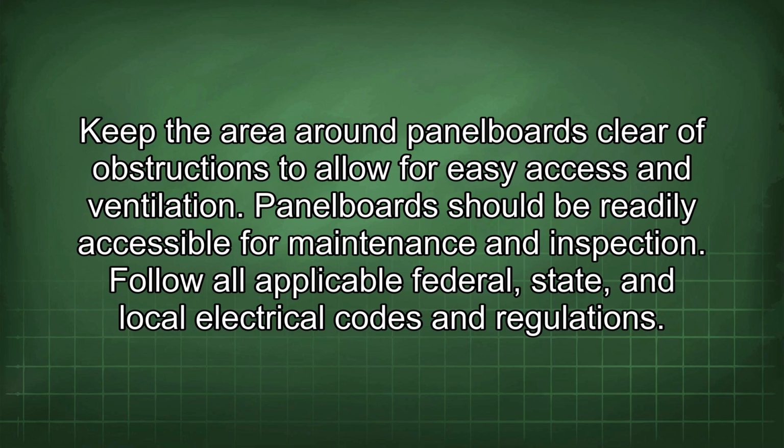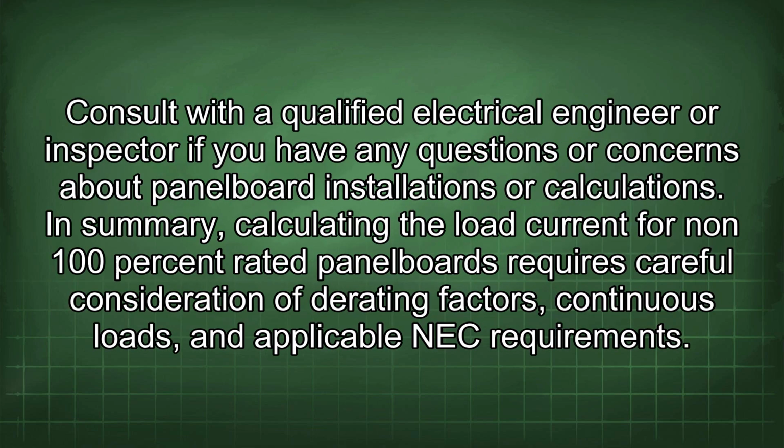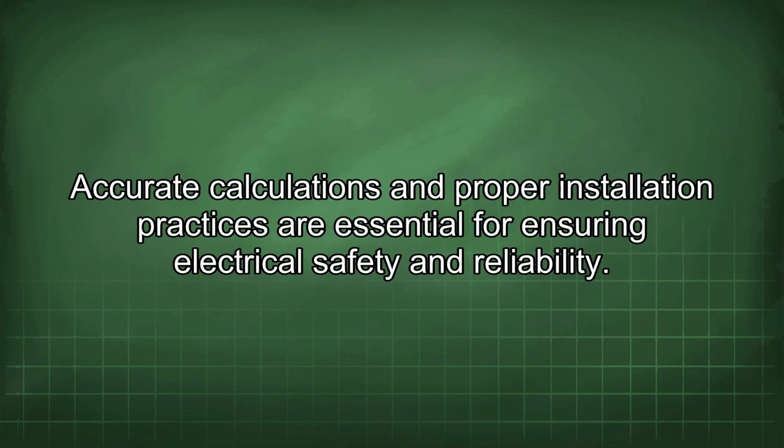Follow all applicable federal, state, and local electrical codes and regulations. Consult with a qualified electrical engineer or inspector if you have any questions or concerns about panel board installations or calculations. In summary, calculating the load current for non-100% rated panel boards requires careful consideration of derating factors, continuous loads, and applicable NEC requirements. Accurate calculations and proper installation practices are essential for ensuring electrical safety and reliability.